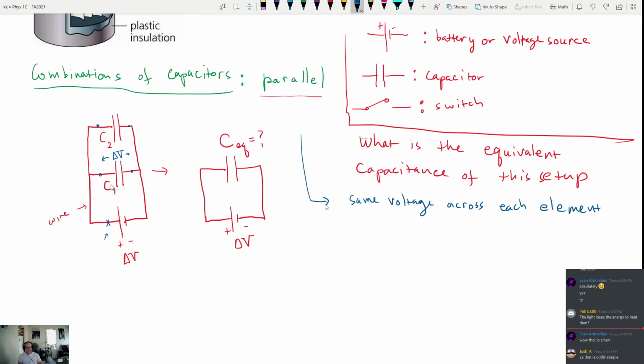And you'll notice that for something to be in parallel, it has to have a connection to the positive side and a connection down to the negative side here, right? And that's why when you plug something into a wall socket, there's two holes: one for the positive side and one for the negative side. And a third hole for ground, but we don't have to worry about that for now. The point is that most devices you just plug in, there's two little prongs, and you plug them in parallel to your home network. That guarantees that every piece of your home network gets the exact same voltage across all elements. The power that comes out of your wall socket has about 110 volts of RMS voltage, and anytime you plug something into the wall, it gets 110 volts. That's just how it works, because everything is plugged in parallel.